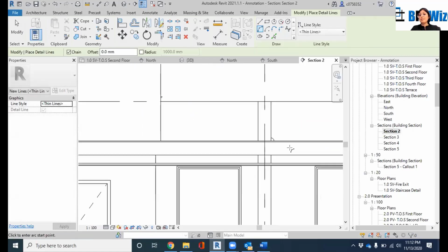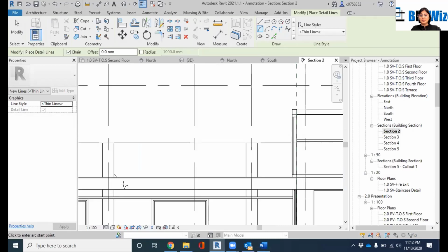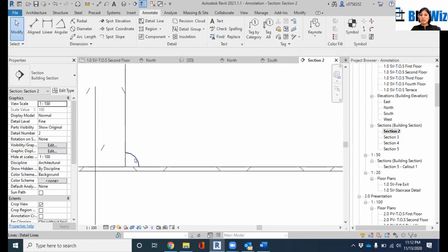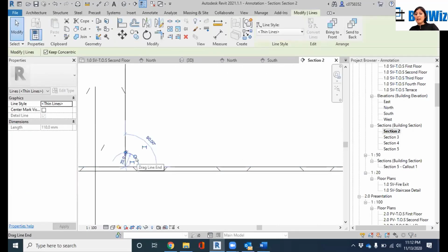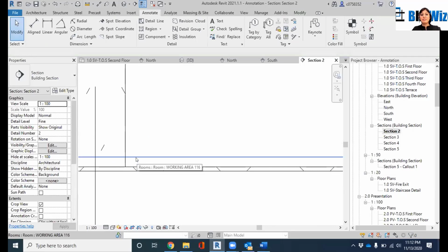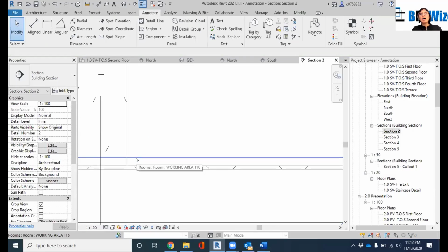I don't have to model this and make my Revit model unnecessarily heavy. Okay, let's say maybe for quantity purposes, I want to model it so that I can know the total parameter of this, and maybe for some quantities I want to do it, then sure, go ahead and do it. But if it's just for showing the details, we can get away with the detail line.